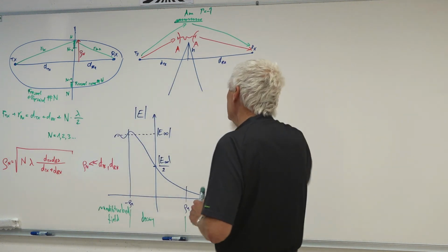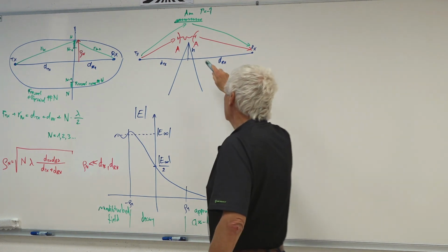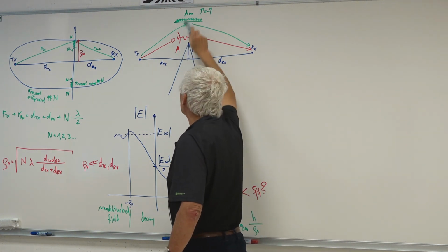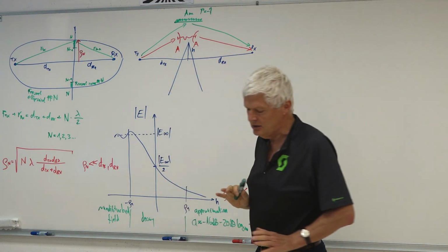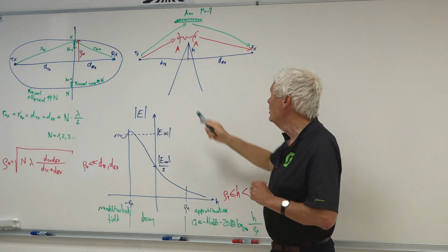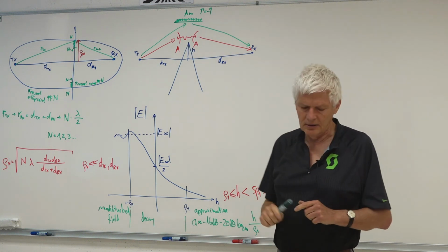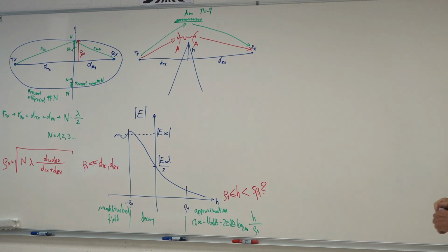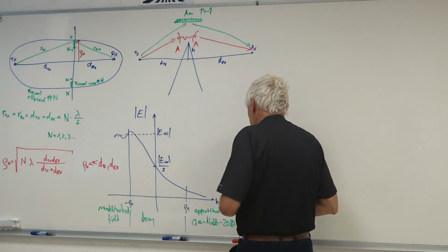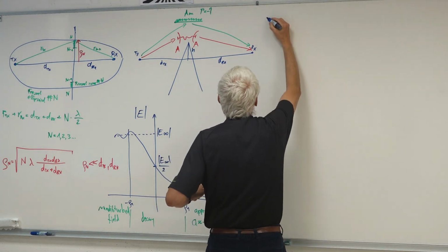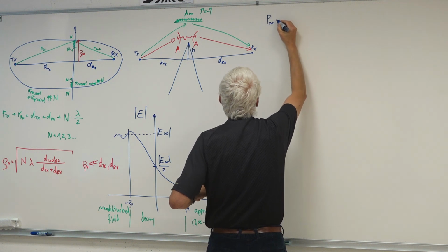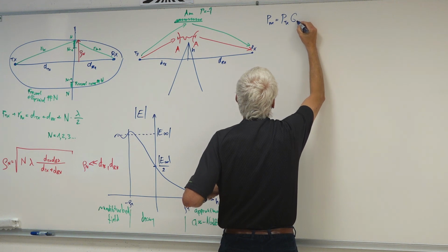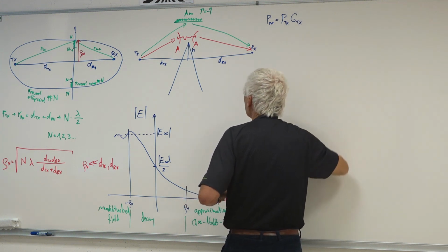So let's try to do the calculations of a link over a mirror, because antennas are much more difficult to manufacture than the mirror. But if they have a comparable area, their efficiency is comparable. So we have comparable efficiency without the complication of building two antennas and connecting them together. What is the power that actually reaches the mirror? The power on the mirror is the power of the transmitter multiplied by the gain of the transmitting antenna.